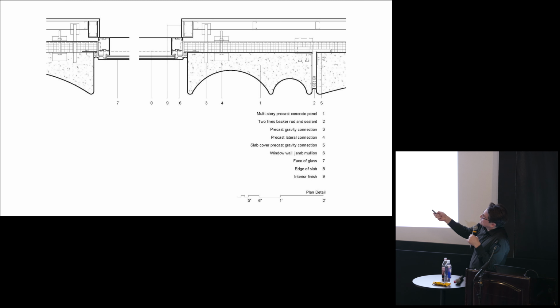This is a detail with this window wall that spans in between, the joints between the panels. I was telling Brad last night, we learned a lot doing this. It turns out a 30-foot panel gravity loads on one slab only, and so that one slab is deflecting a lot. And the other slabs, which are carrying the window wall, are not deflecting. And so the window wall is not moving, but the whole pier is moving, right?